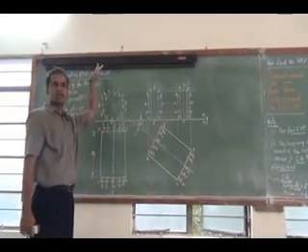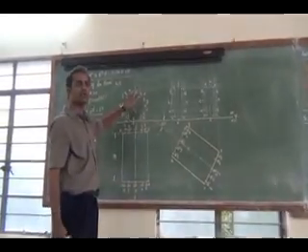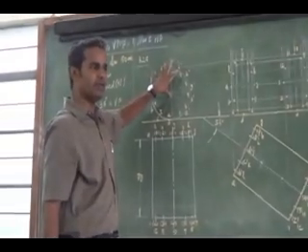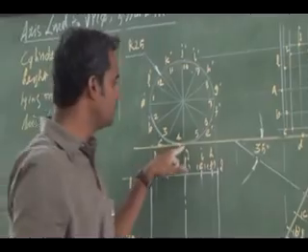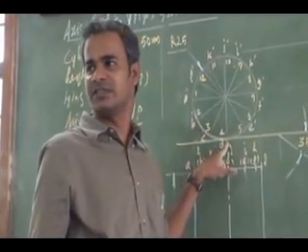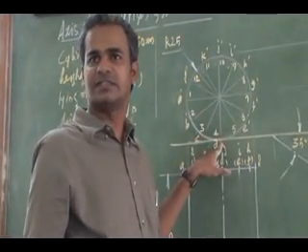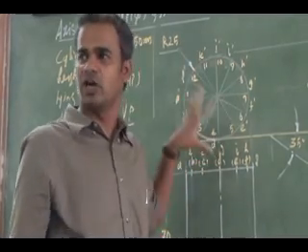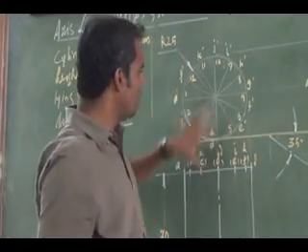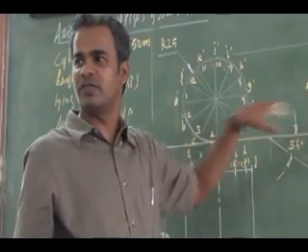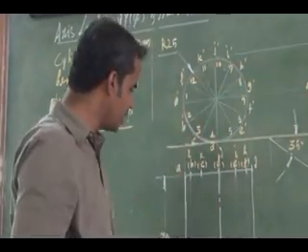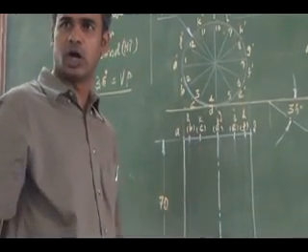The axis is inclined and it is lying on the ground. I have drawn the true shape of the circle on VP. The axis is inclined to VP, and at the same time it is touching the reference line, since it is lying on the ground. So how can I draw the circle? Once you draw the circle touching the reference line, you can proceed for the simple top view.